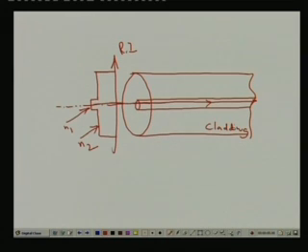This I talked about, the single mode step index fiber. There is a step change of the refractive index, please note. That is the reason we are calling it single mode step index fiber, because there is only one mode that light can transmit through the core. Core diameter is usually very small.